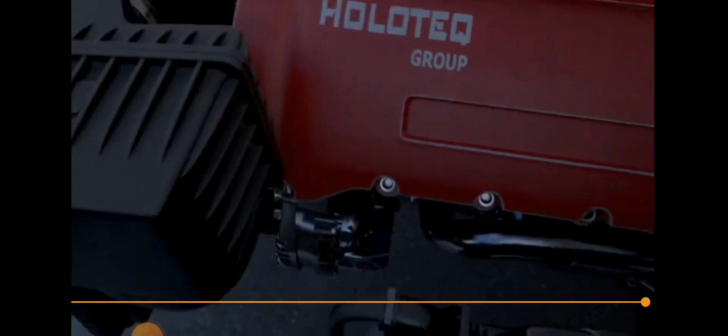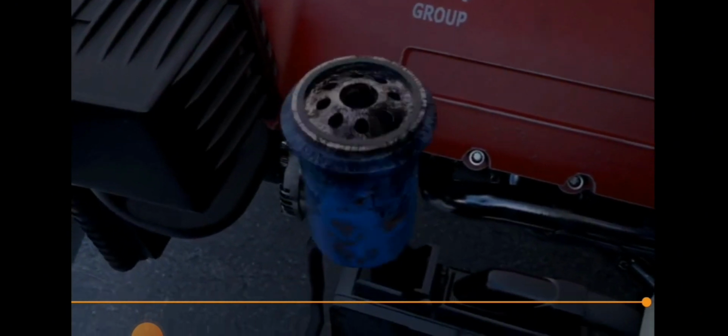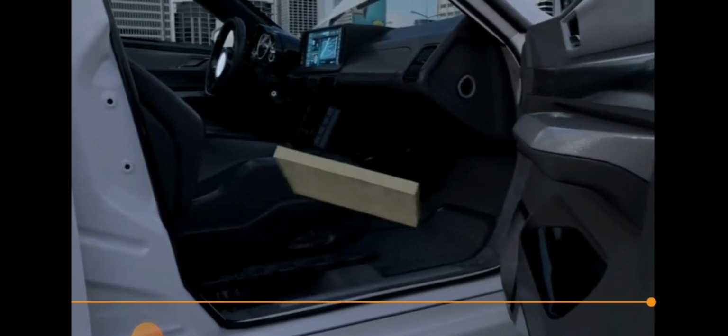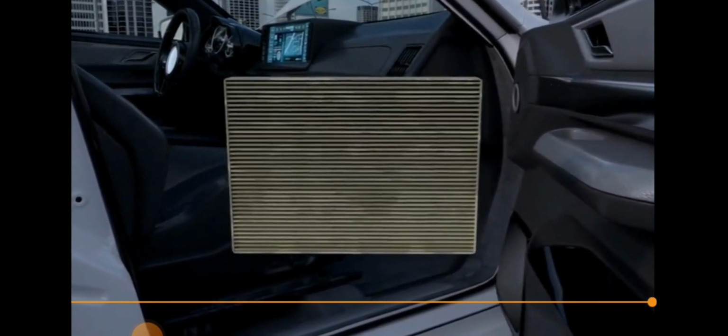Engine oil filter. It must be replaced after each 2 replacements of oil, where it drains engine oil of impurities resulted from friction inside the engine. Gearbox oil filter. It is used only in automatic transmission vehicles and must be replaced according to manufacturer instructions with each replacement of transmission oil. Air condition filter. It is replaced when air quantity in passenger's compartment is few and its flow is low.